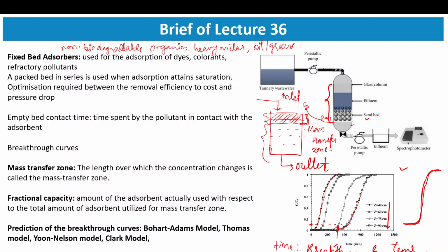So one term for it is empty bed contact time, which is a measure of the time spent by the pollutant in contact with the adsorbent, right? So the more the contact time, the more time for the pollutant to interact, and the more will be the efficiency, or the adsorbent will be utilized more efficiently.